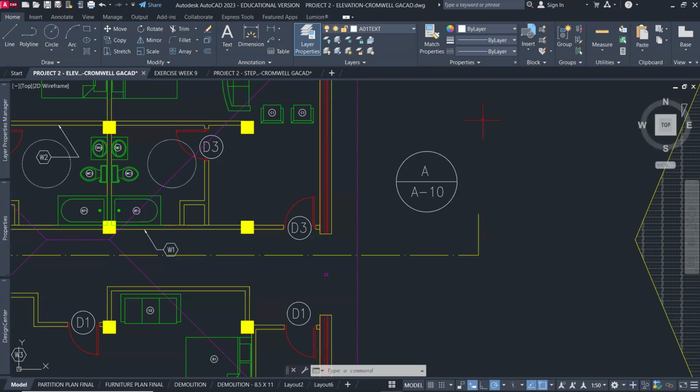And then creating the arrow. So I'm just going to maybe make a line from the quadrant up by maybe this much. And then I'm going to say tangent, right? So it should be tangent to this line. There you go. And I'm just going to extend that. Or sorry, extend this or fillet.